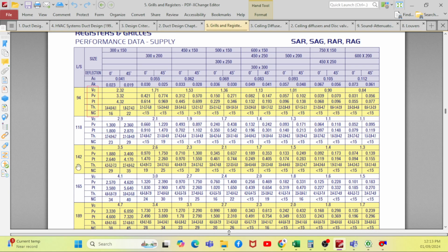So for this particular airflow rate and this particular size, you have to select to match with this pressure drop. If I have a supply grill and return grill, 7.4 and 7.4, so it will be 15. Then if I go with VCD 5 Pascal, 6 Pascal, then it will be supply 1 VCD, return 1 VCD, 12 Pascal. So 12 plus 15, 27 Pascal. Then I have an elbow, say 5 Pascal. Then I have ducting. All the values will be within 50 Pascal, so that you are able to choose that particular model. If you want to choose the next model, your size will increase.